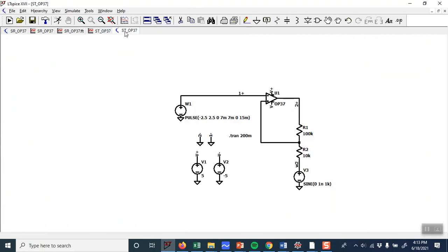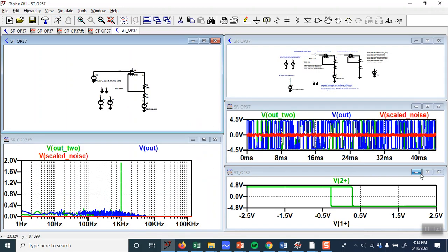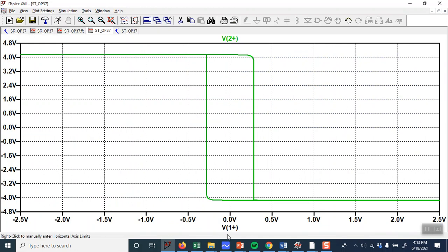coming back here, right, this is just a Schmidt trigger where this is a triangle wave, and let's just run this and we see that's the input, this is the output, and we can see our two trigger points, and I believe I calculated it in the lab manual. It's about 0.6 in simulation, this hysteresis width, right?